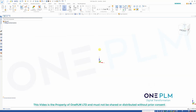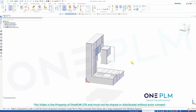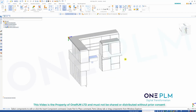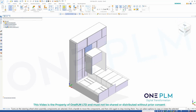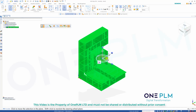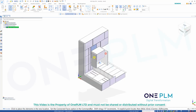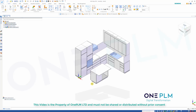We're not going to get prompted assembly or part. CAD Direct will bring it in the way it is. So we can see our kitchen's come in. That's the wrong way around. So let's get to our home position, make sure move on select is on, select the sub-assembly, use shift and click on the plane in the middle of the steering wheel, and then use that steering wheel to spin that round 90 degrees, that looks like.